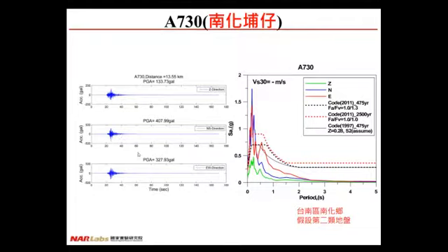But what I want to point your attention to is near the 0.5 to 0.7 seconds, there is a pulse, predominantly in the east-west. Could this be related to what Kevin was mentioning, this velocity pulse? We don't know, but we have a strong suspicion it may be.